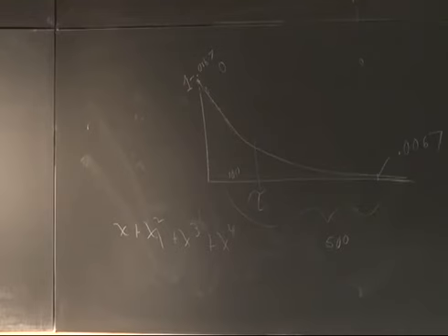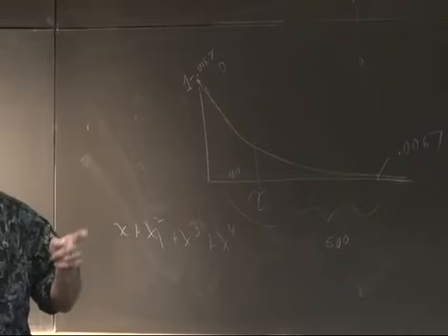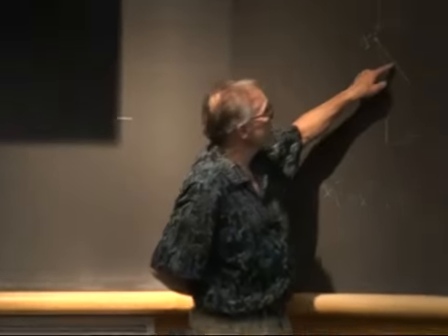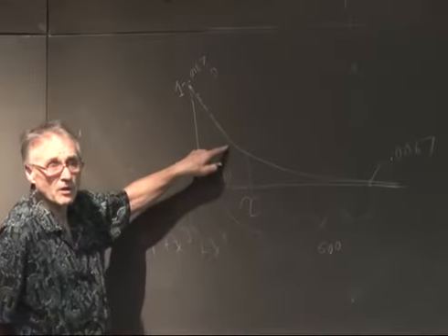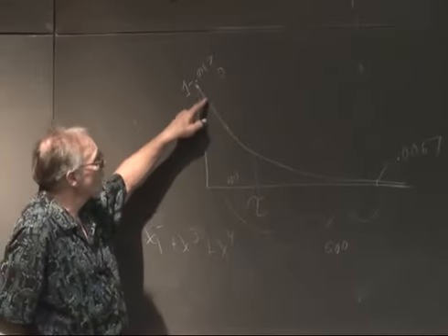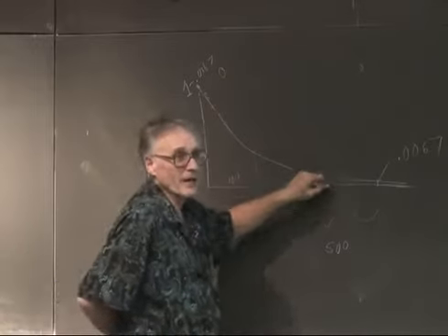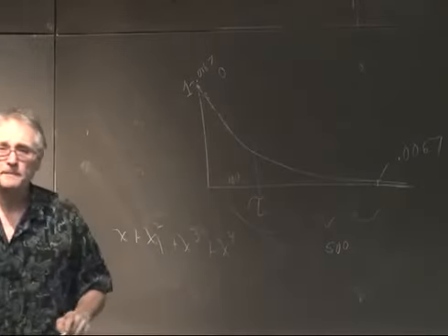So one last thing we need to do: when we do the direct digital synthesis, we're going to, of course, fractionally step through this table. So we may step very slowly through the table if the time constant is long, and we may step very quickly through the table, maybe skipping every other point, if the time constant is very short.